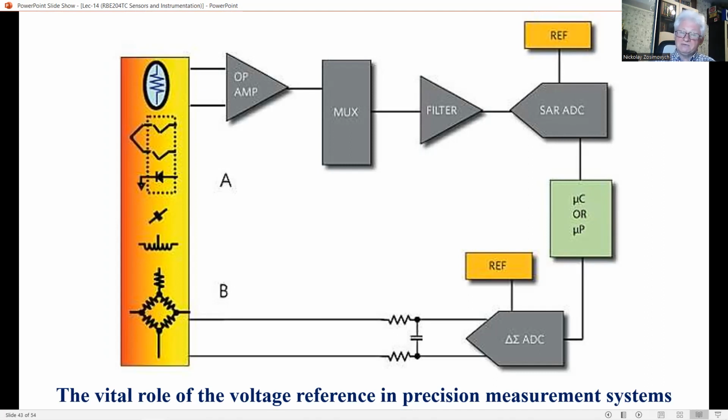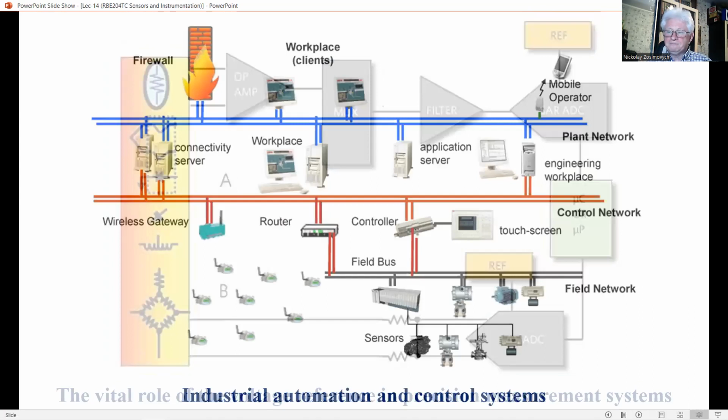A less expensive but slower alternative would be to timeshare this expensive equipment by using a multiplexer. This device will pick one channel of data from a bank of data channels in a sequential manner and connect it to a common input device.